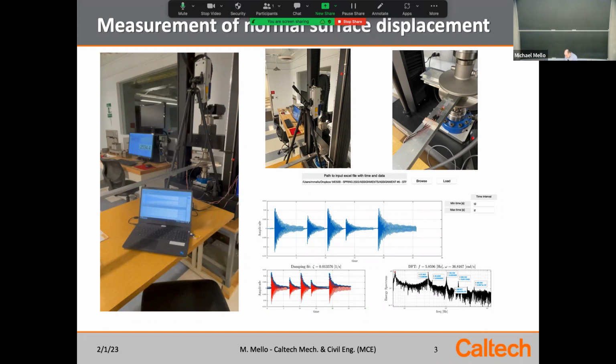And you'll have ANSYS predict what the vibrational frequency of that beam should be, or the mode should be. And then it's fun to go in the lab and see some of those very things through measurement, okay? Now, I could have just as easily not shown you this vibration equipment and told you that that strain gauge on the beam reported to us vibrating strain signal, right? So even though we've been using it in the static sense so far, where we've been deflecting a cantilever, or I've been asking you to imagine how it works, the strain gauge is an absolutely dynamic sensor.